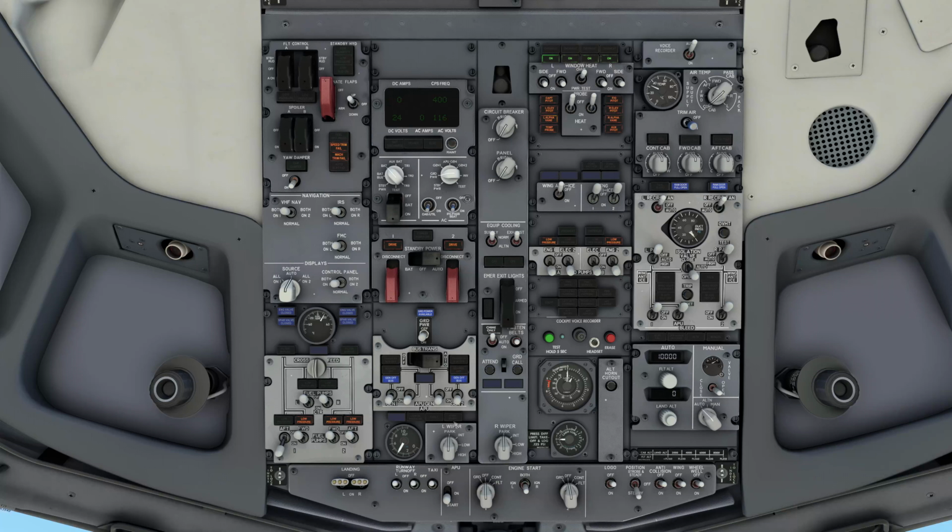And that is good. So after 1 minute, we can turn on the APU bleed, which we will do. But I'm going to come up here and turn the left and right packs to auto. You'll hear the air start flowing in the back. I'm going to come up here to the isolation valve, make sure it is open, and then we're going to turn on the two recirculation fans and get them going. So there's the aircraft basically turned on.